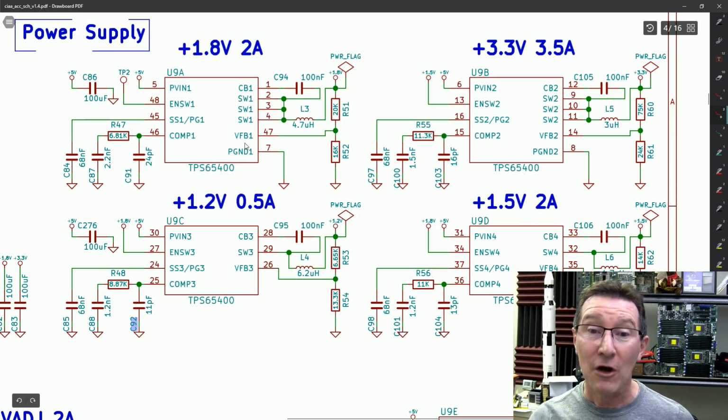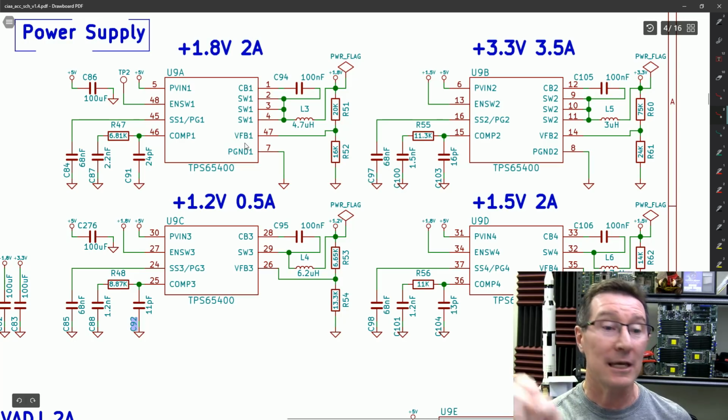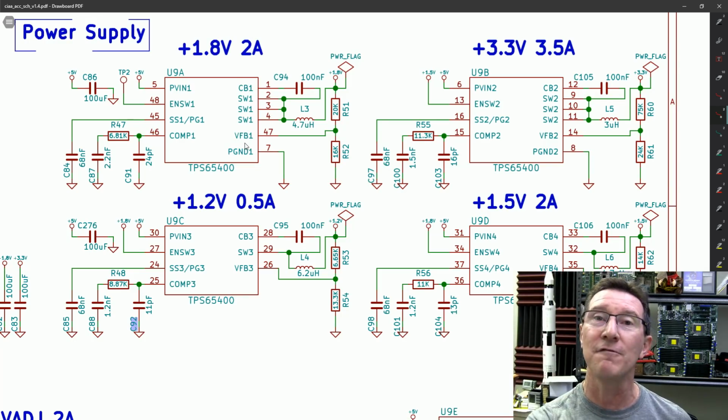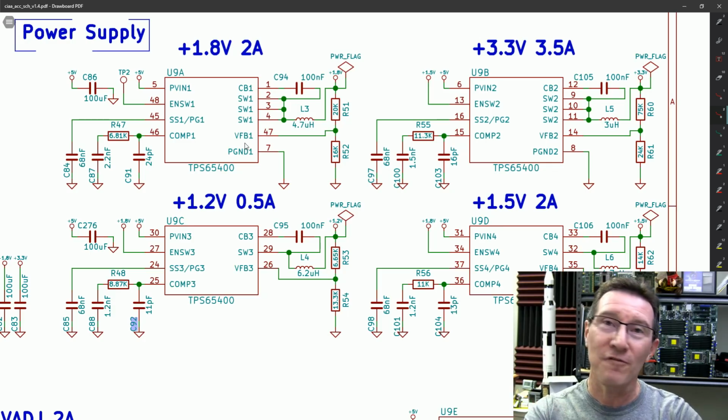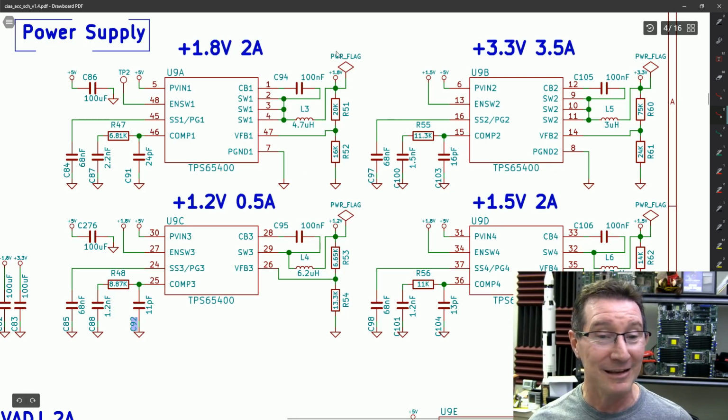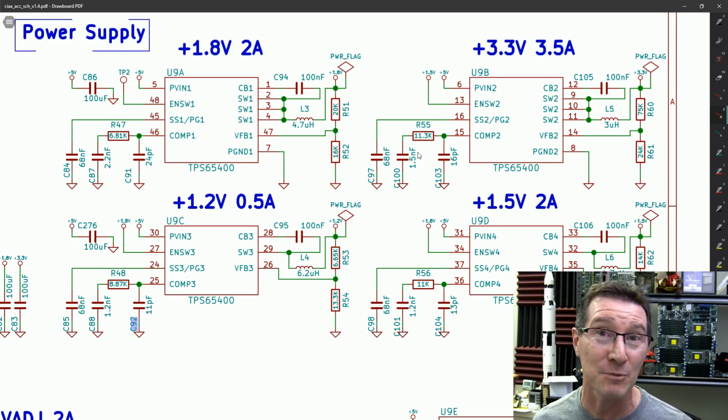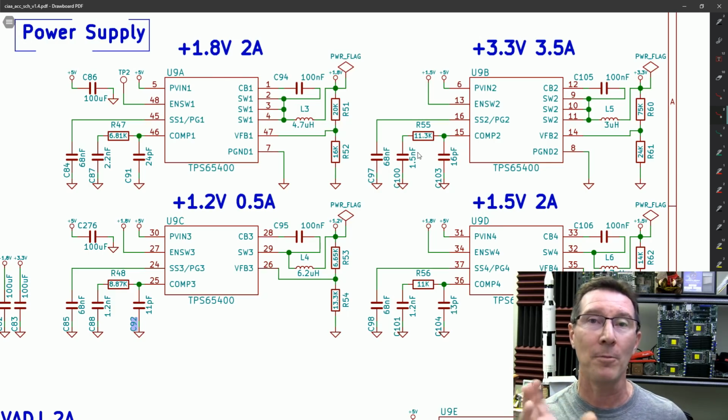So yeah, just go through, read your data sheets again, go through your calculations, reevaluate, do your engineering evaluation, and all the stuff that goes along with qualifying your design and everything else. And almost every project I've ever done, and it might be the odd exception, but a vast majority, I've been able to BOM optimize in some way when it comes to capacitor and resistor values.